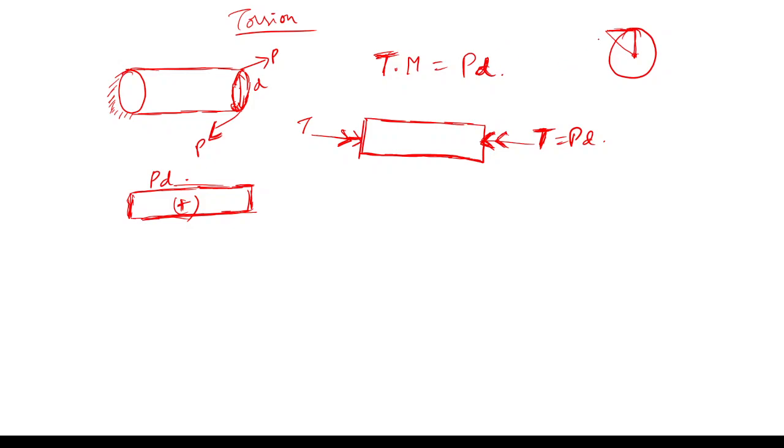You can intuitively imagine, right? For example, when I'm twisting a solid rubber while holding one end of the rubber, a small twist I am giving, not a big twist, you can see at the center there is no deviation with respect to its shape, whereas at the periphery of the free end, it will suffer the maximum distortion.